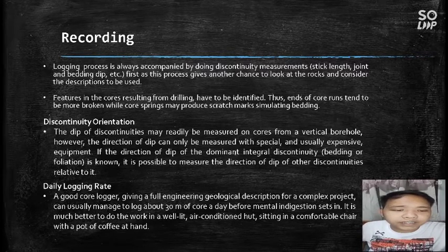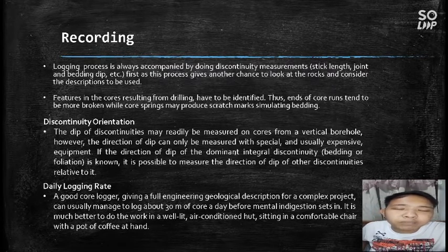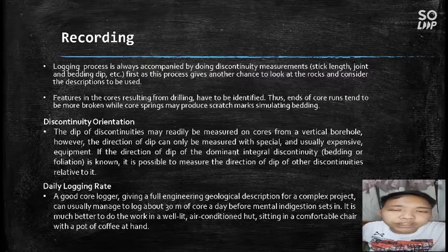Next is the daily logging rate. A good core logger giving a full engineering geological description for a complex project can usually manage to log about 30 meters of core a day before the mental indigestion sets in. It is much better to do the work in a well-lit, air-conditioned hut, sitting in a comfortable chair with a pot of coffee at hand.